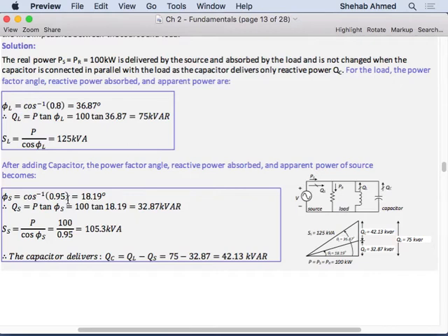Not very efficient from a power transfer perspective, I would say. But this is what we have. But again, home consumers are not really what's consuming reactive power in the system. What's consuming reactive power is all the big motors and machines that we have in Ras Laffan, in Mesaieed, in Dukhan. That's why the utility forces them to regulate the power factor. For us, the utility can put small capacitors in the substations close to our neighborhoods, and that will take care of maintaining the power factor at a reasonable value.